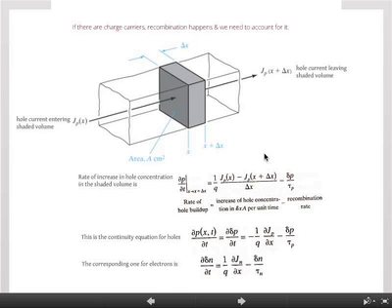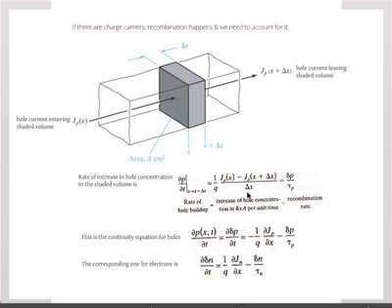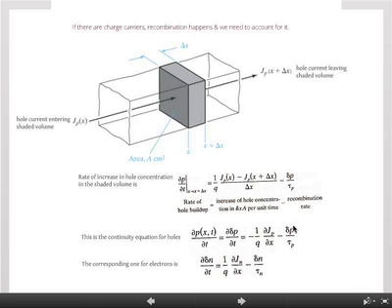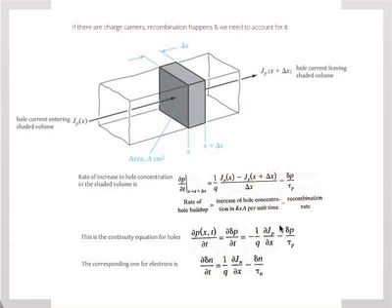Now, of course, we can apply differential calculus by making delta x very small, and this becomes a partial differential equation, as shown here. And that's the so-called continuity equation for holes. This is an important concept because we can use this to explain the behavior of almost any devices. These are the basic ideas which we will use to derive the properties of the devices later on. Okay, and the ideas are very straightforward.